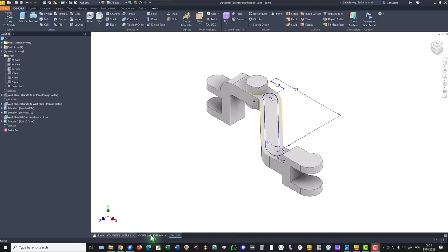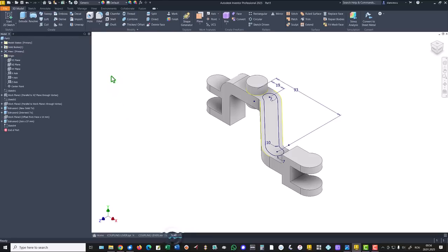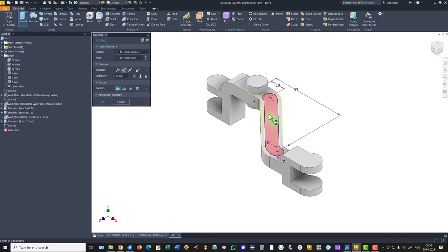And the depth of the pocket is here. 8 is this dimension, 14 is this dimension. We have to place an expression. Extrude of this with cut on a distance of 14 minus 8 divided by 2.